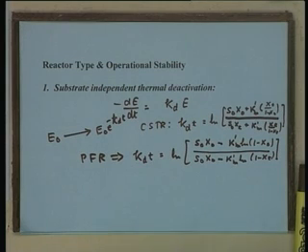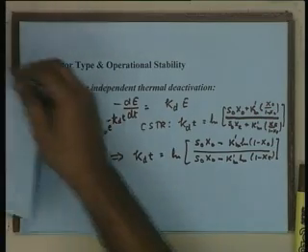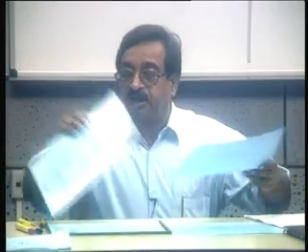If the substrate deactivation is not linked to the substrate concentration, then in such a case the CSTR will be a desirable parameter. On the other hand, if you look at the other kinetic pattern of thermal deactivation, this is also a very common situation, because in most cases it is understood that the enzyme is more stable in the presence of its substrate. So, the higher the substrate concentration, the more the thermal stability, and its Kd value is much less in the